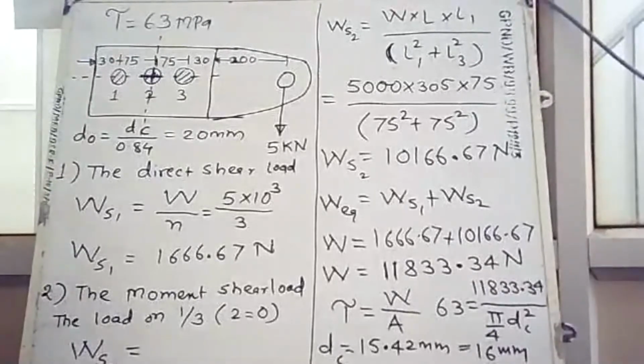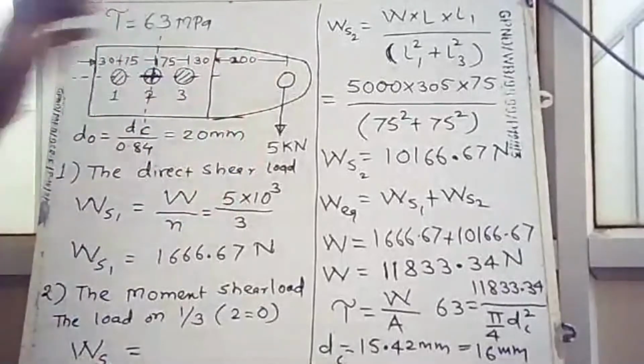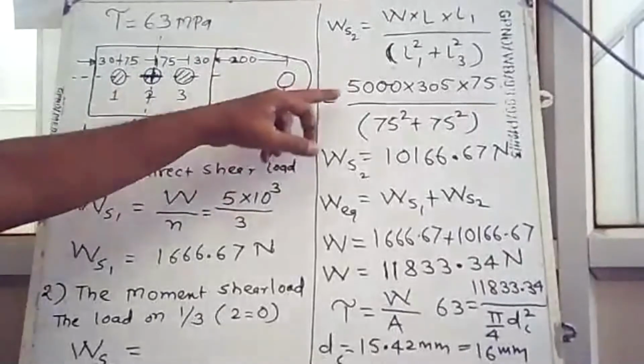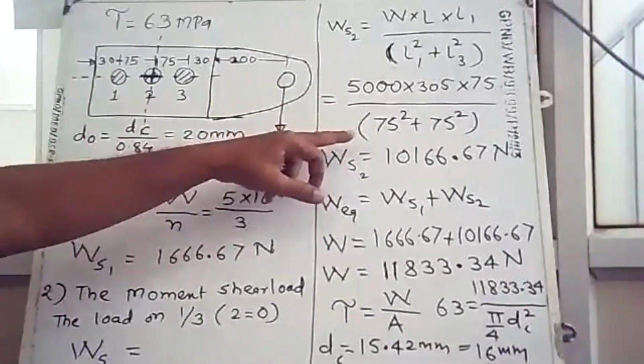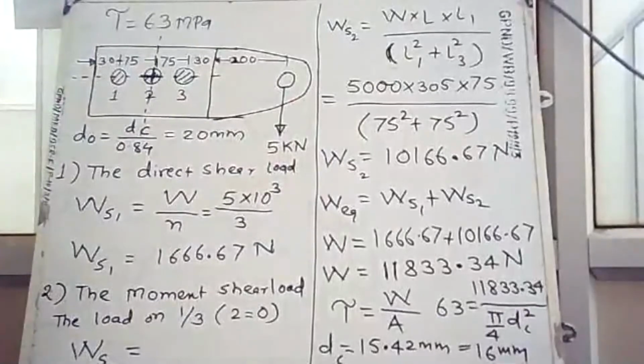the second or third type of eccentric loading problem, in which the load axis is not in plane with the bolt axis. There may be chances that instead of 3 bolts, there may be 4 bolts or 6 bolts. So we have to consider the radius, or L1, L2, L3 distance, from the center of rotation of that complete plate.